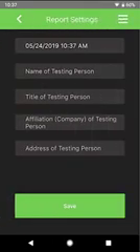Press the Send icon at the lower right to generate a report. Before generating the PDF report, you will be presented with a report settings screen where you can fill in specific information about the job. The information is saved for each particular job, and reports can be generated whenever needed, such as when new readings have been taken. Select the upper right menu icon to generate the PDF or the upper left arrow icon to exit back to the job screen.